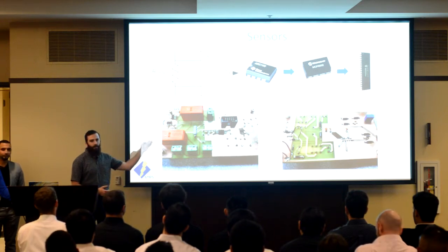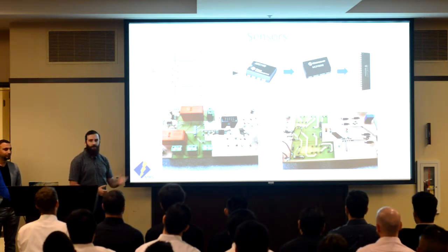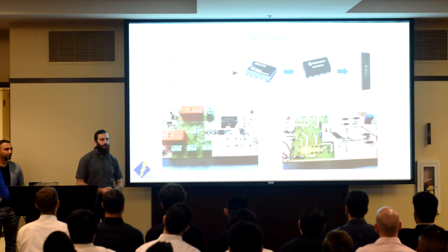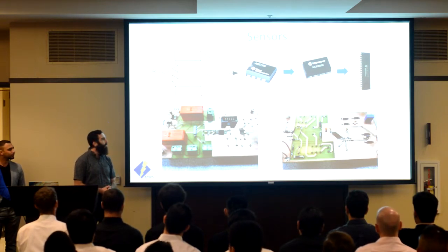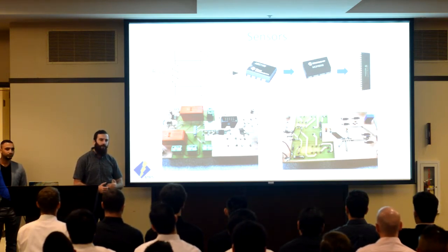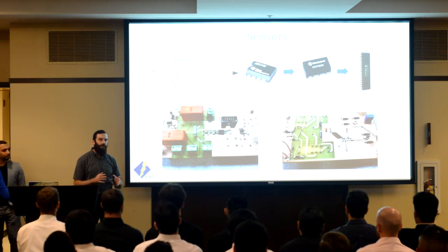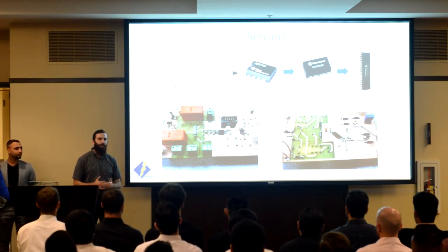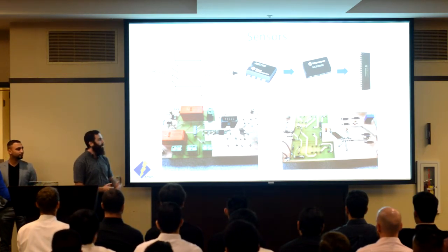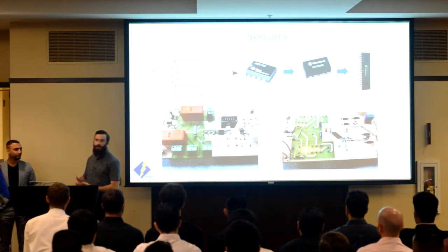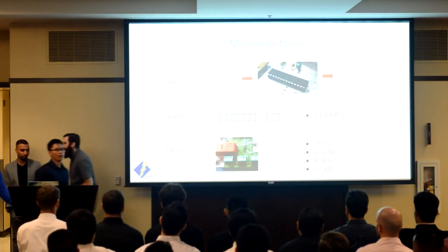After that, we take the output of that amplifier and feed it into a pretty standard op amp. We use the Microchip MCP602 here, and we use that to do a little bit of level shifting and further amplification to get our signal into a perfect 0 to 3.3 volt range, which can be sampled by our microcontroller, which Luke is going to tell you about next.